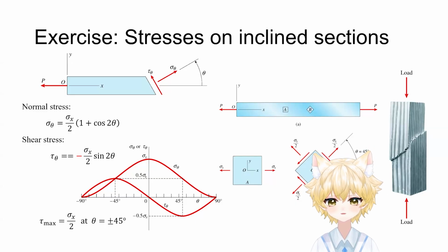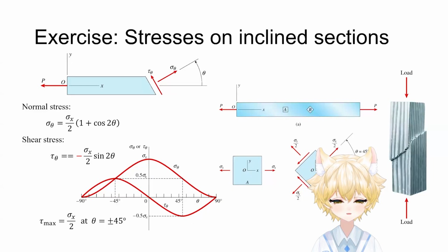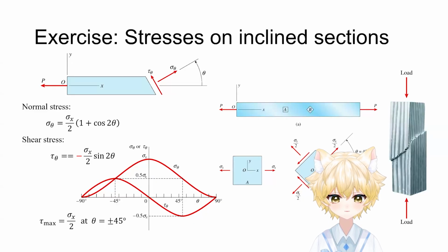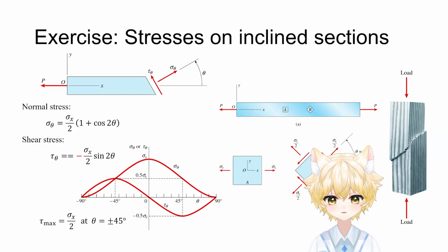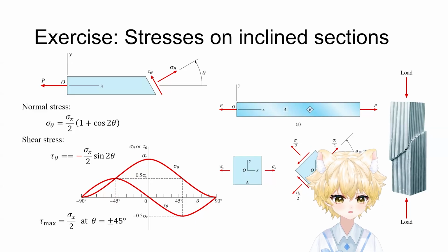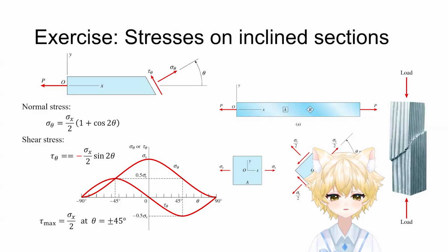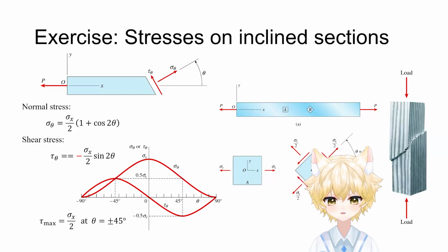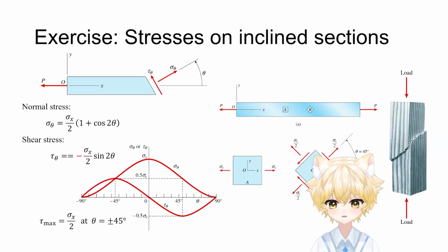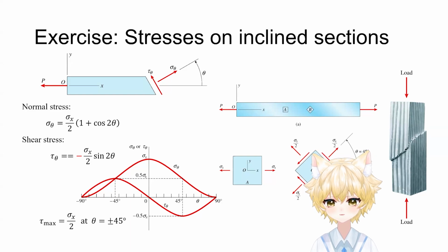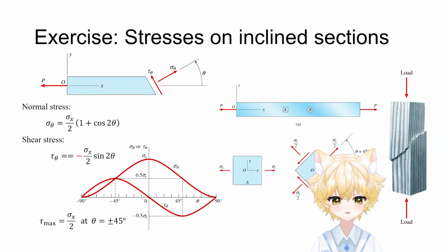Even when they are just being pulled or pushed straight, right? You apply an axial load, but you get failure on a 45 degree angle. Why? Because even though the load is axial, the internal mechanics generate a peak shear on the 45 degree plane as we calculated, right? If the material is weak in shear, that is exactly where it will break.